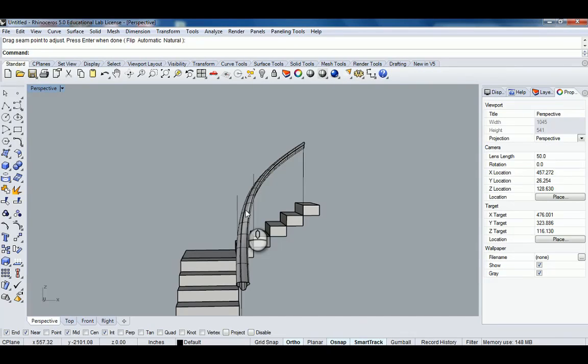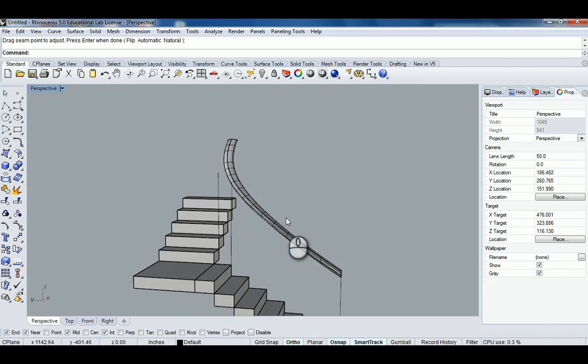After you did divide the curve, just to make it like a perfect curve, because it doesn't make it a perfect curve, like some sticks out. Some sticks out when you've done the sweep? Yeah. Okay. In some cases, that's going to be because the turn that it's trying to make is too tight for the radius of the curve that you've made.